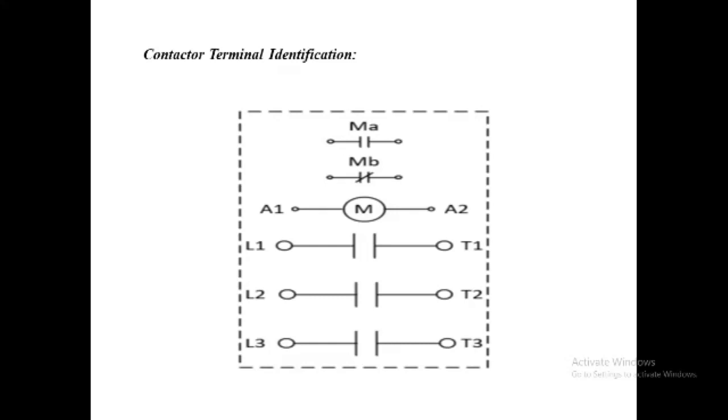As the motor speed increases to rated speed, the current will drop down to the nameplate current rating. A contactor rated for use in a motor circuit must be rated to carry the full load amperes continuously, and it must be able to carry much higher starting current. General purpose contactors and relays are not required to carry the highest starting current that a motor requires.